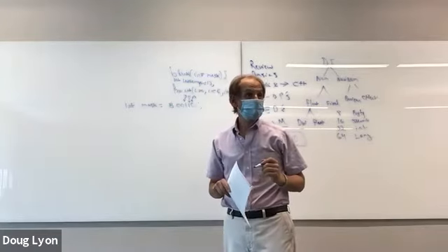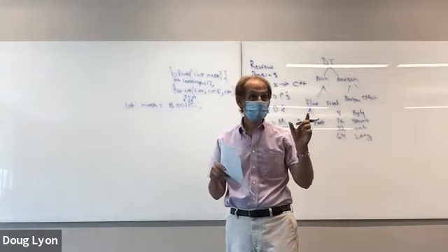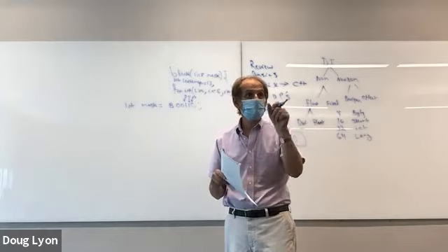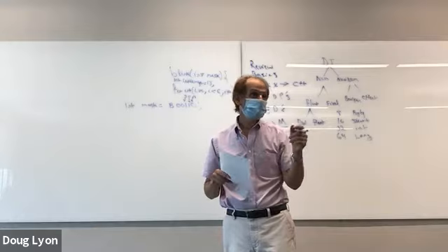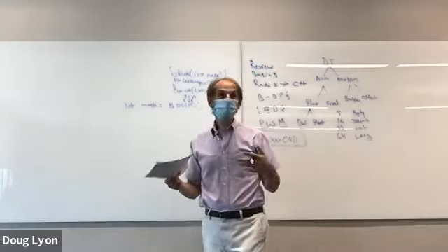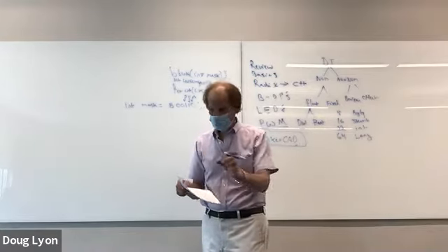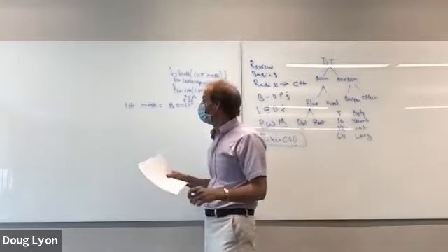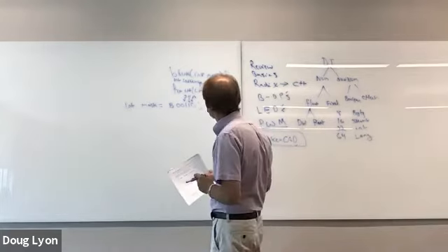And so what we're going to do is encode the LED display inside of a single binary number. Then inside of blink, we're going to decode that number and figure out which of the LEDs is on. This is a critical thing that you're going to end up doing time and again whenever you get into embedded programming, because you'll be reading in things like dip switch settings, you'll be reading in all kinds of codes from various devices, and you're going to need to find ways in which to decode these things.